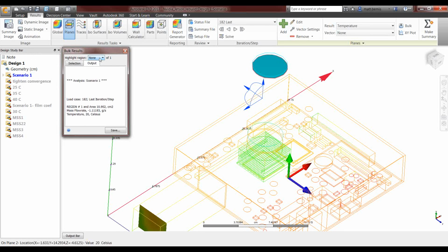Do we ever run into issues with pressure and thus convergence in regards to the sealed box within the natural convection domain? Typically, we don't. If the mesh is fine enough to capture the flow, typically the pressure is not an issue. Yeah, I think that's something that occurred. I think I did face that, but I was using quite an outdated version of CFD. There's different little tricks there. It's been a while, but I believe at one point I put a zero pressure on a solid on the inside. I guess it's something to try.